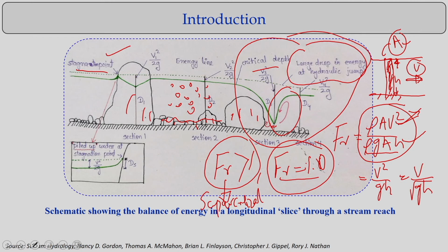So, we use hydraulic jumps as a design for energy dissipation or for creating turbulent structures for mixing of any fluid, or fluid and sediment mixing. We use a hydraulic jump as an energy dissipator, or as a mixing of these flow systems. That is how we use the hydraulic jump concept.